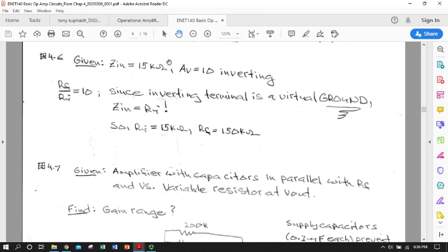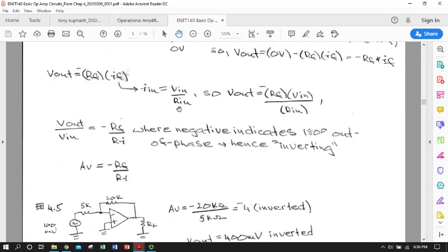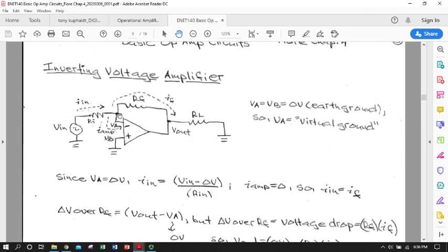We've got that virtual ground. So when we look at input impedance to the inverting amplifier, we'll scale right back to it. One thing we have to remember is this terminal, even though it has infinite input impedance into the amplifier and no direct path to true earth ground, it's a virtual ground. So it counts as a path to ground for the input.